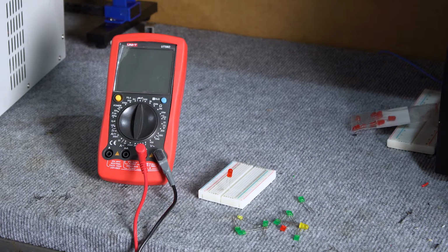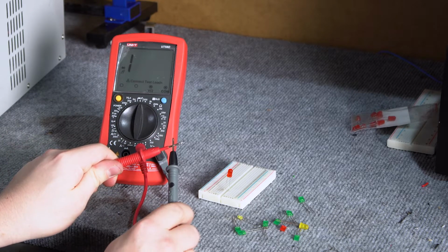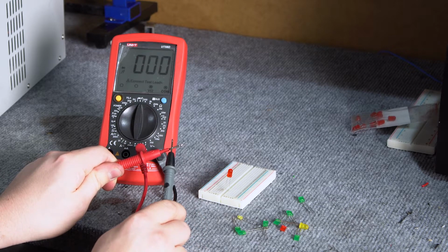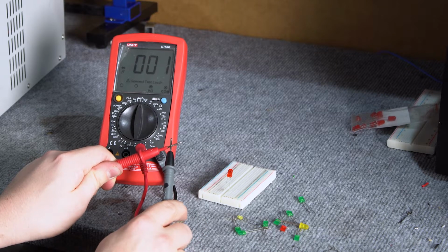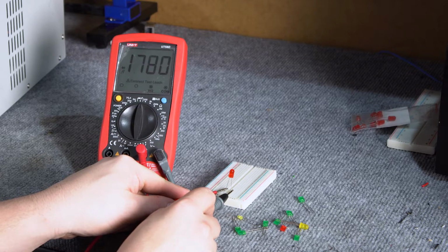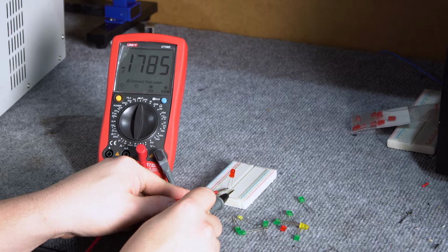The diode and continuity tester is used to check whether, after connecting to a given semiconductor element, a voltage drop is presented on it. It is worth noting that many meters use voltage sources in their construction with a value of approximately 1–2 volts, some even 4 volts. Thanks to the increased voltage, we can check LEDs, but this has one disadvantage. Voltage with such values may cause the switching on of some elements and the flow of currents, which may affect the state of the tested element.